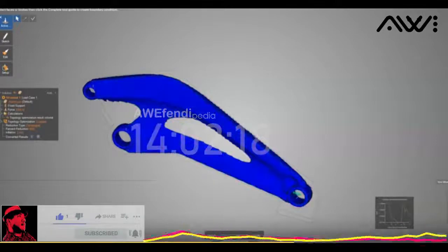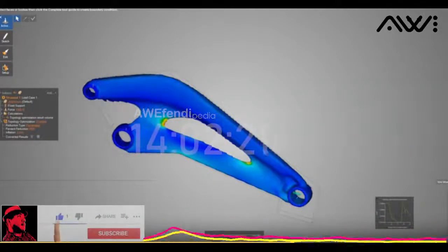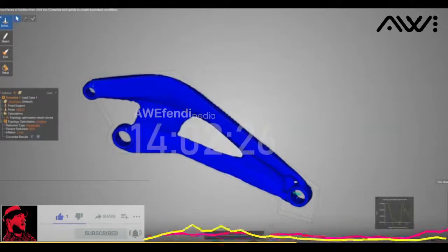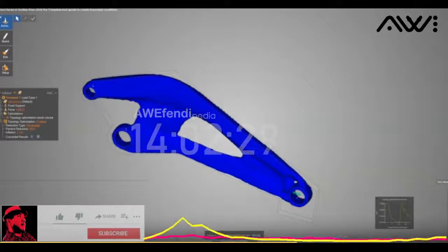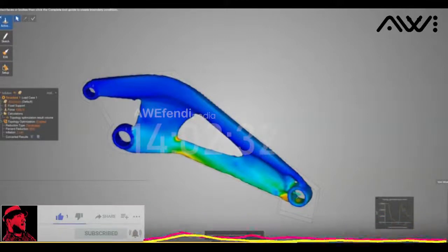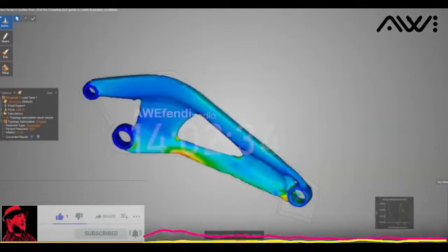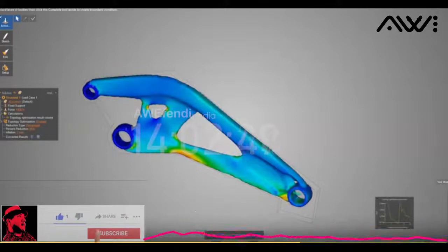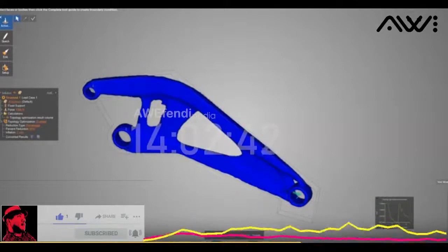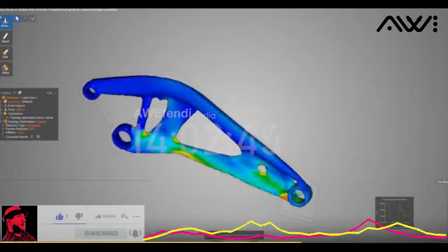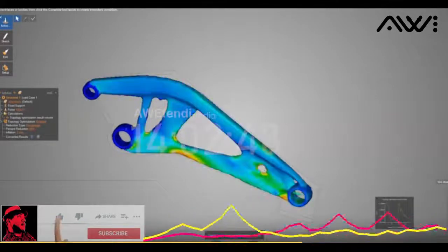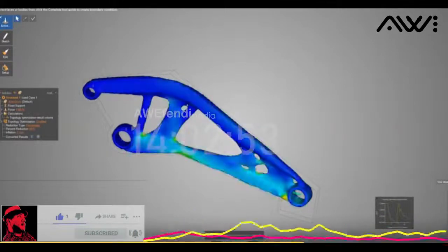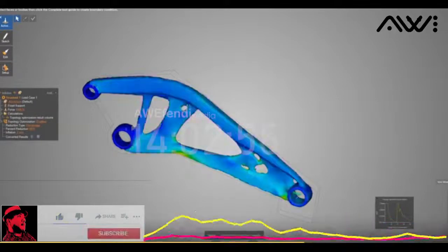So the goal here, what I'm trying to show you is, not only can we do it based off one to quickly get an idea, but as we start understanding our design constraints, and realize we're going to have forces in all these different areas, you can see how quickly we can do this. All this is real time. I'm not hiding anything. I'm getting an idea of what's going on here. And the nice thing is I can just hit stop, go back, make a change, add a cut, and have these what if scenarios of what if I did change this design. It's a great way to go through this process and understand, am I going on the right track?